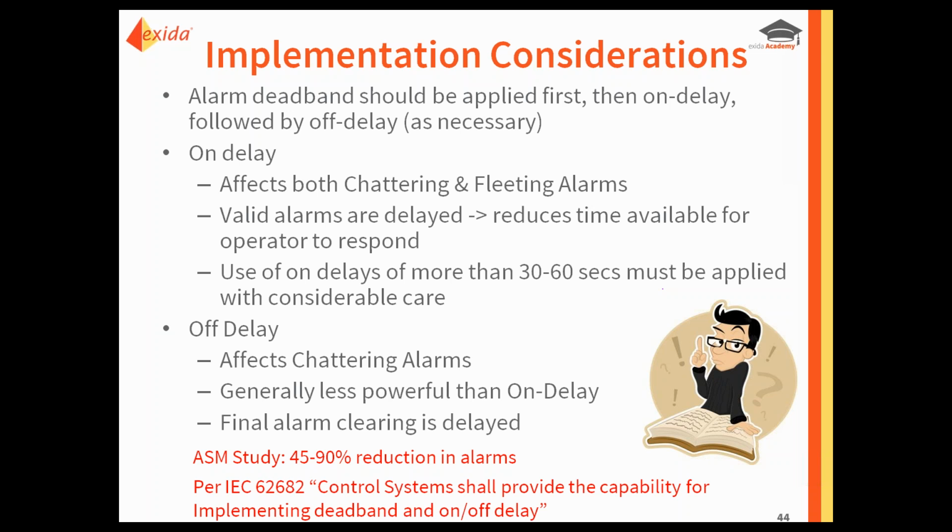Now, why would that be in the standard? Well, that's because folks recognized how important or how integral these tools can be as an easy way to reduce the alarm load and clean up nuisance alarms. So that's actually a requirement for control systems to have going forward.